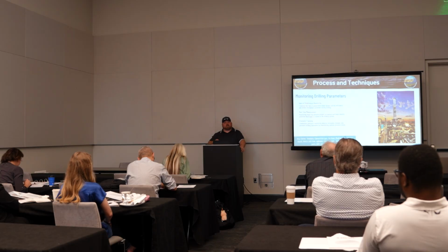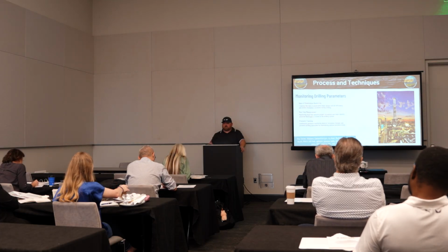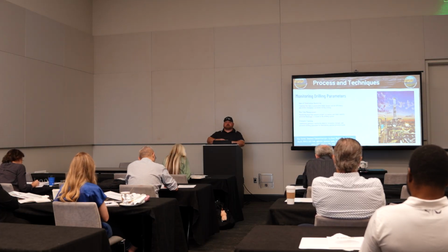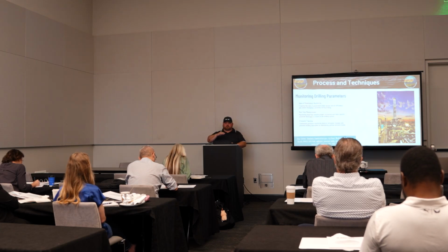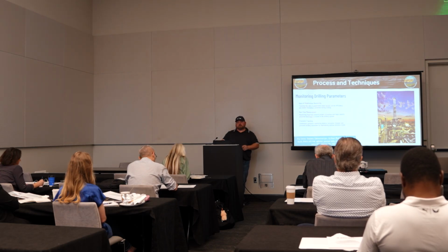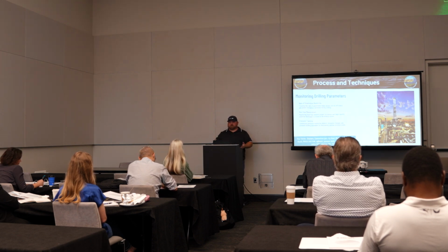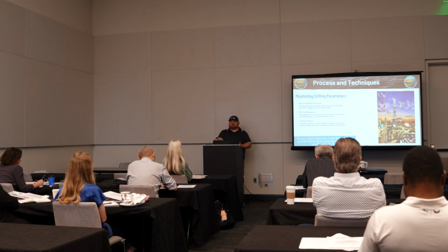In water-based mud, it's a lot higher, because it's thinner mud. The viscosity is way thinner, so the gas is able to escape on its own. So you need your agitator up higher in the mud, because if you get a small loss of circulation and the fluid drops in the possum belly, you're going to lose all your gas for that little bit of time, and it may be permanent, it may not. You just have to adjust your agitator to compensate for that.